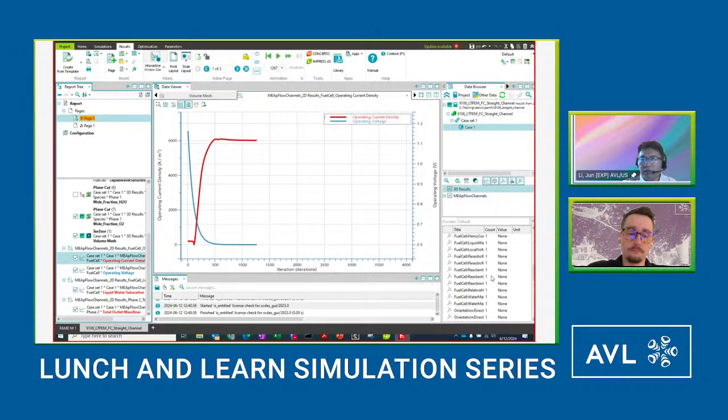You can already see here the 3D results side. A PEM fuel cell is a pretty complicated thing to solve, so there are a lot of results in here: the temperature, potential, the species, and the water. So the 3D can help us solve, for example, flow or media non-uniformity issues, and look at the water and heat management in a single cell and then in a stack. And then look at the local degradation effect in these 3D settings.